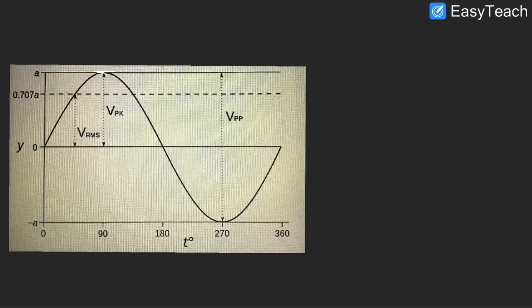And based on that, for a periodic sinusoidal signal, we have a value called the RMS voltage, or the effective value. The expression for your Vrms or V effective is your V peak, denoted by Vp, divided by root 2. This is a very important expression that you would probably use in solving most of the problems. So your Vrms is your peak voltage divided by root 2.